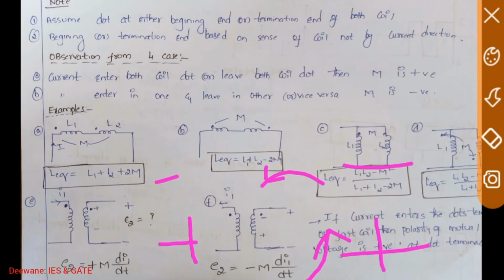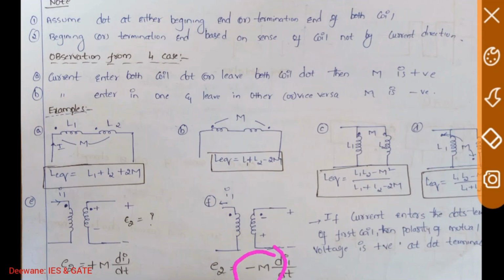But see how the direction at the terminal is given. It is given opposite. Lenz law is not satisfied. So what do you keep here? You keep a negative sign: E equals minus N d phi by dt. So once again, listen, you need not always say that minus N d phi by dt is correct. Minus N d phi by dt is correct only because it depends upon the terminal polarity.